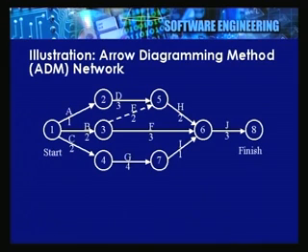Now, again look at the particular activity E, look at the diagram on the board. Activity E, for instance, is a dummy activity, okay, and from that particular point of view, there is a mistake. It should not be showing any kind of value on it, but this indicates that if two activities are likely to have the same starting and finishing nodes, we may need to add a dummy activity to make sure that the diagramming notations are conformed to.